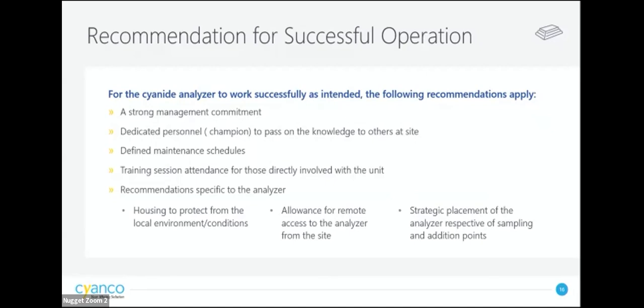It also requires well-trained and dedicated personnel, and a defined maintenance schedule executed in a timely manner. There are also operational considerations, including housing for the analyzer to protect it from the environment, and remote access to be able to reach the analyzer for troubleshooting.